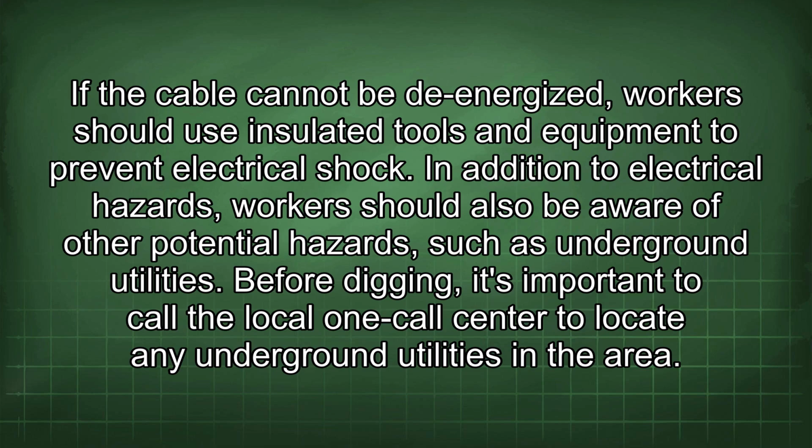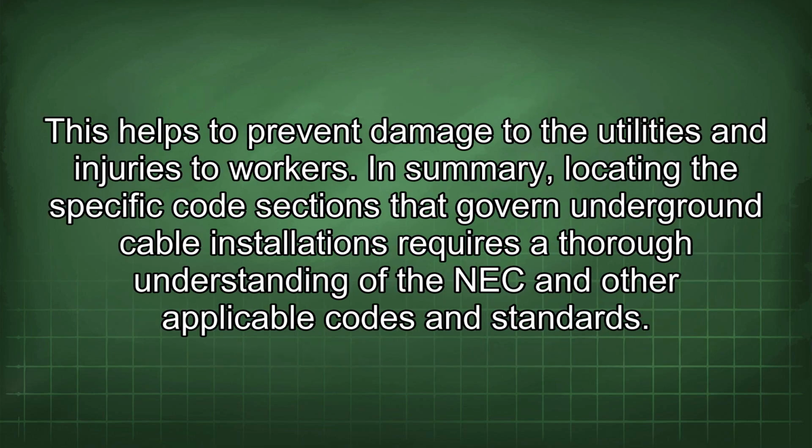In addition to electrical hazards, workers should also be aware of other potential hazards, such as underground utilities. Before digging, it's important to call the local one-call center to locate any underground utilities in the area. This helps to prevent damage to the utilities and injuries to workers.